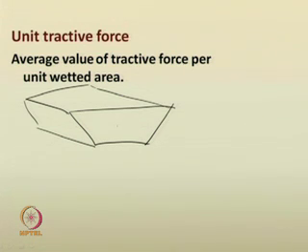However, for any bed material, the tractive force, as we suggested earlier, is rho g A L sin theta, which is equal to rho g A L S naught for uniform flow. This was described earlier. The same tractive force is acting on the wetted area of the entire reach.